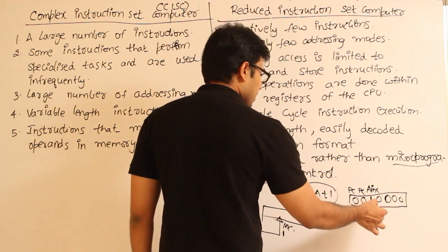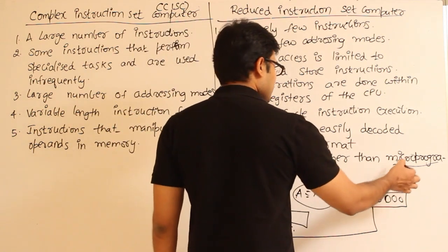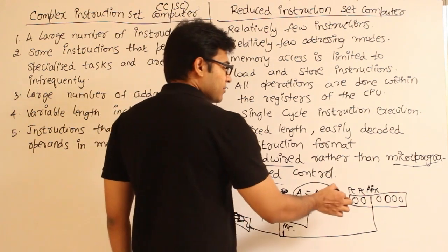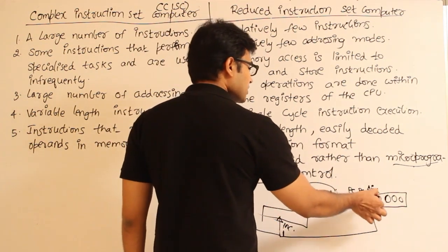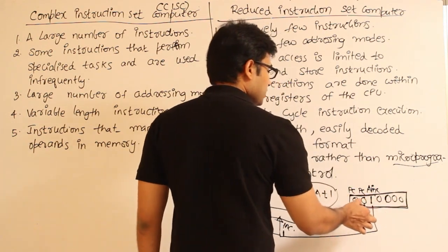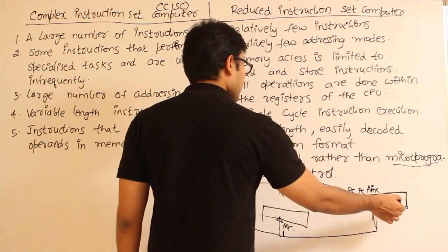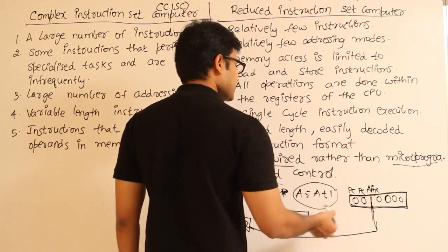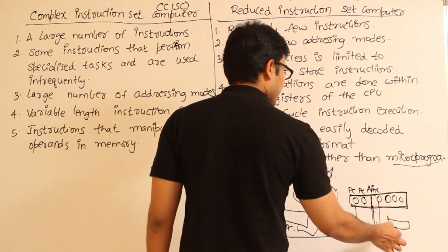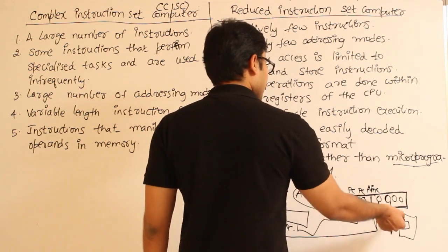And now they will be connected to the corresponding inputs like this. So in order to execute an instruction in a microprogrammed environment, we simply load a word into a register which is called the microprogram instruction register. And that register will be giving us the corresponding zeros and ones, and they will be connected appropriately to all the registers and the other circuits. So depending on what this word is, they will be generated.